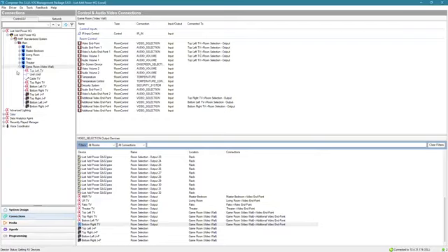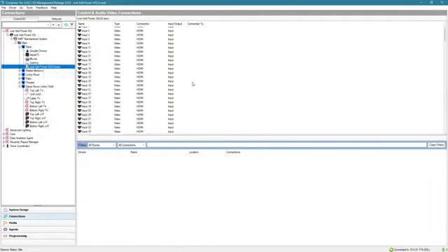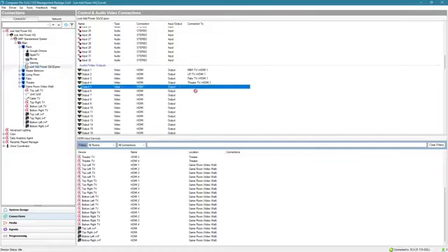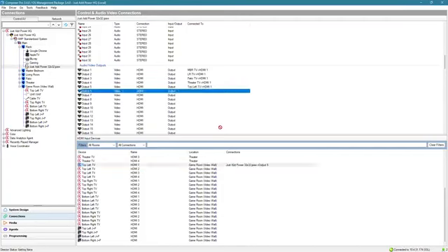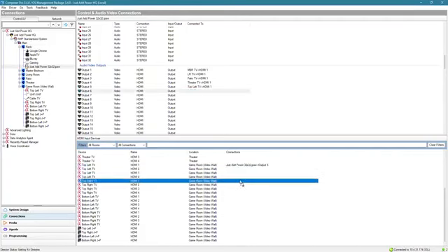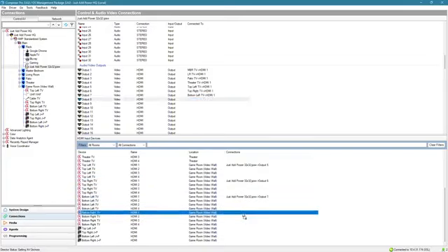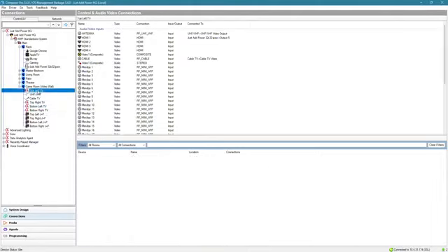The other thing we need to do, because these are new displays in our system, is we need to go to the Just Add Power driver. We need to go down to outputs, and we need to assign the TVs as new outputs for the system. So we've got HDMI 1 connected on all of those. Top right HDMI 1, bottom left, and bottom right. And all of these connections are to the TV drivers themselves. The Just Add Power receiver drivers are in there, but they're not used in the connections portion because, again, the connections are used for volume, power, all of that, and that is the TV driver that you've loaded.